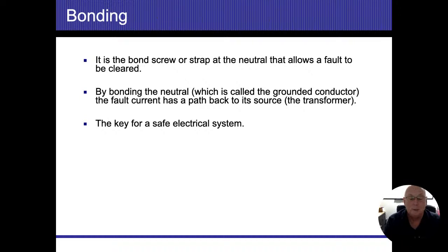So no splices, number 6 or number 2, 150 amps is my line in the sand. Nothing else shares in the conduit with it. In Chicago, we have something called a Chicago ground, and they did that in a lot of the suburbs around here as well. They'll come out of the electrical box, usually at the first means of disconnect, and go to the closest water pipe. When they get to the closest water pipe, that's where they attach their grounding electrode conductor to that water pipe.